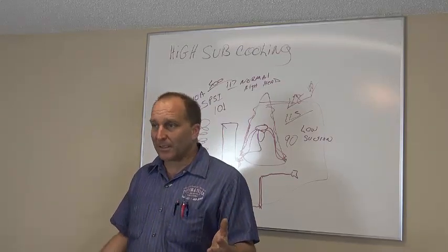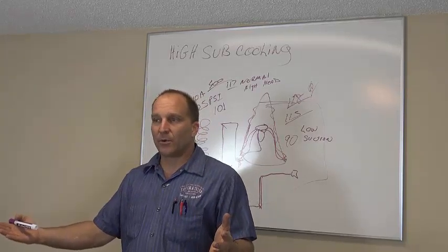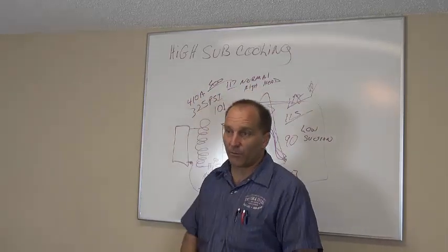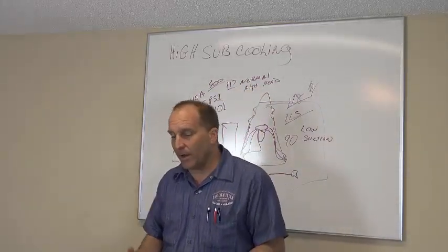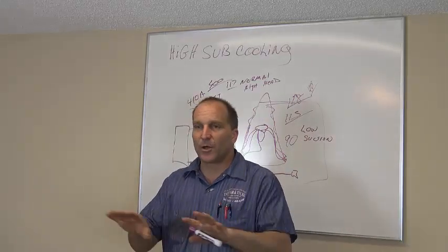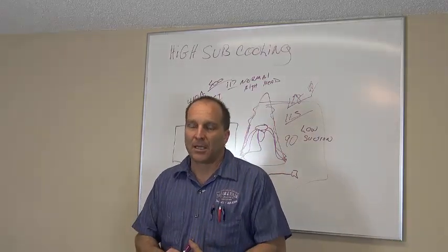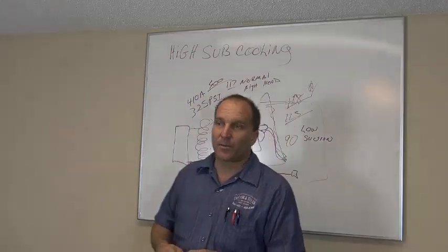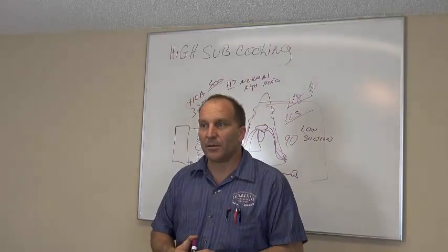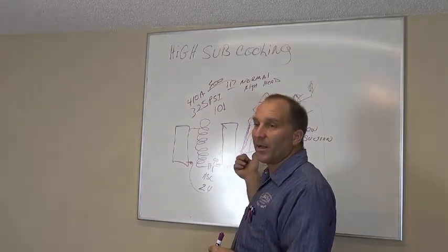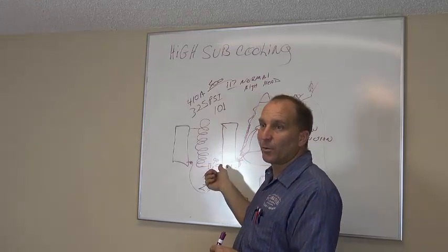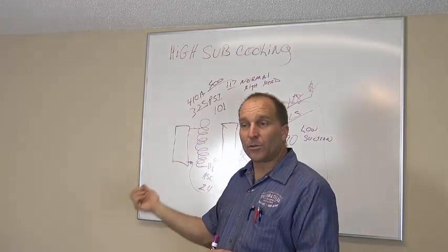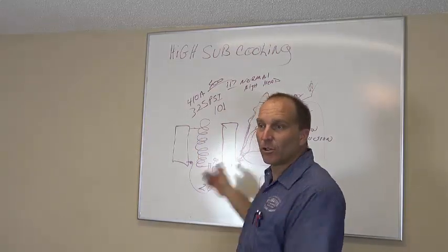Let's say you bring your subcooling up to 10 to 12 degrees. You got that 325-pound head pressure that the system's calling for, and you're sitting there going, okay, subcooling's at 10, 12 degrees. I'm good. See you later. I'm going home. Well, what if you got a slight restriction inside your TXV, or it's not opening up enough? Then your superheat's not going to be proper, right? If your expansion valve's not opening up enough, that's going to cause your subcooling to prematurely get to 10 to 12 degrees, isn't it? So if you don't check your superheat, you don't know what your coil's doing, right?